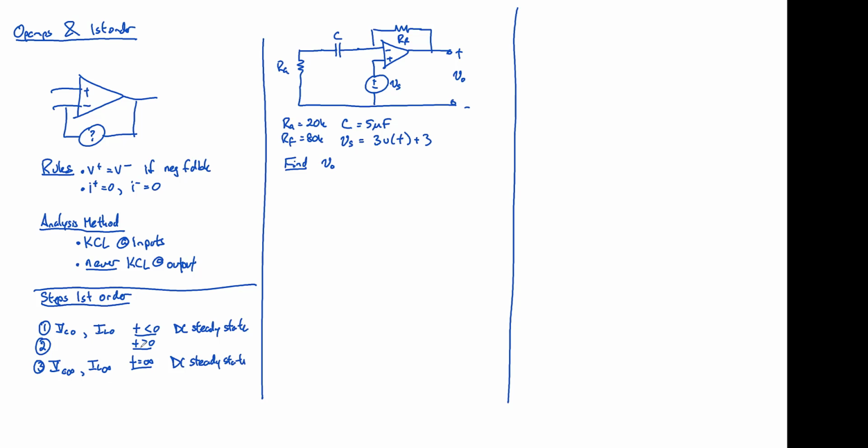But when you're drawing it for time greater than 0, you're trying to find something specific. It's not a current. It's not a voltage. I don't know what it's called. It looks like a T, but there's no top to it. That's Tau, the time constant. Okay, and then your fourth step is to plug it into your standard formula.